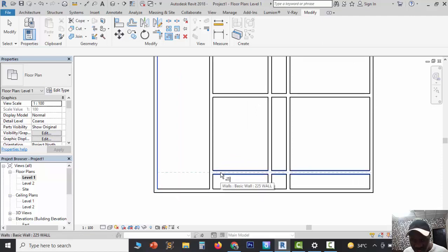So if I select it to go and hit it, you can see this dotted line shows that it's going there. And I can still use it to trim if I want to trim it. If I want to trim this guy, I'll select the crossing edge first. The command is selected. I'll select this. So I want to trim off this side. I'll select the side that will remain.